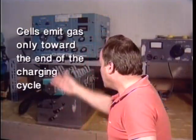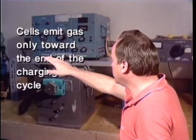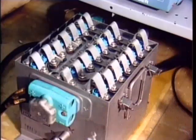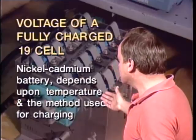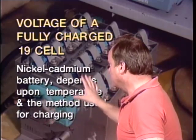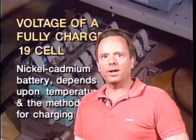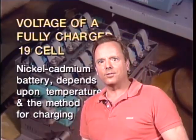When do NiCad batteries tend to emit gas? Well, the cells of NiCad batteries emit gas only towards the end of the charging cycle. We talked about that earlier. Now on the test, they're going to ask you what determines the cell voltage of a fully charged 19-cell nickel-cadmium battery. And the answer is temperature and the method used for charging determine the cell voltage. So it can vary. Cell voltage normally varies from about 1.45 volts to 1.58 volts, and that's determined by the method for charging and the temperature.